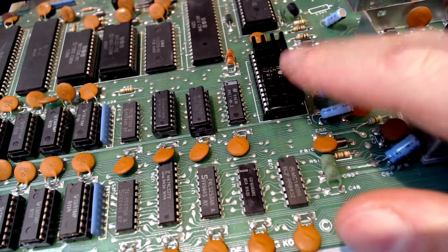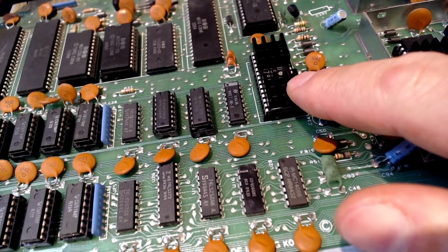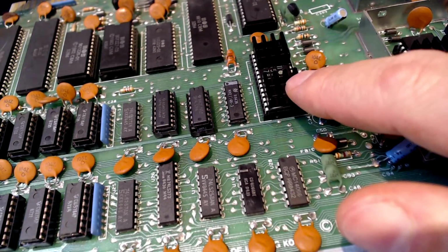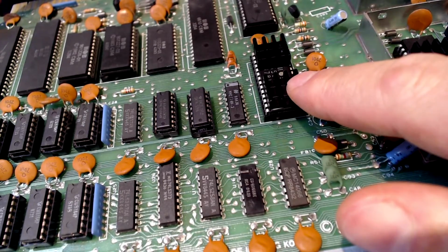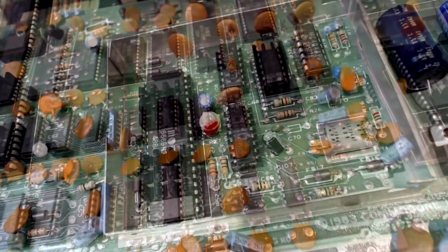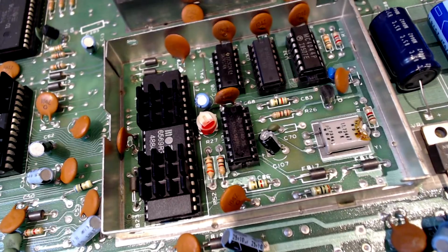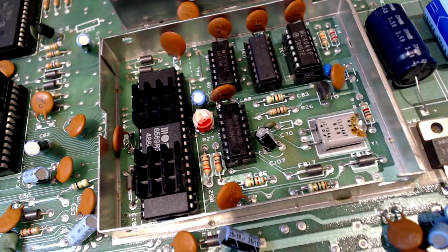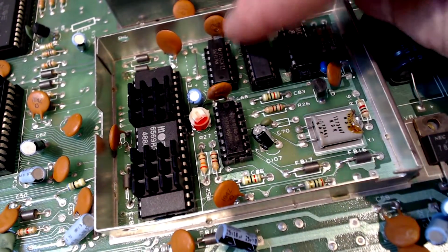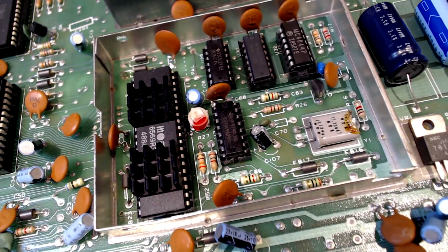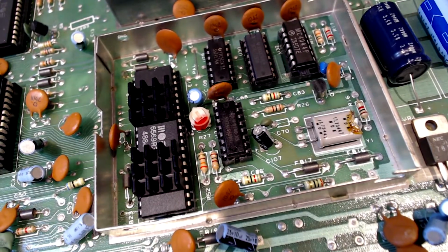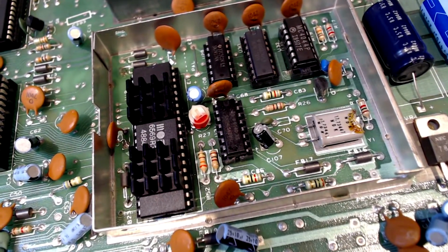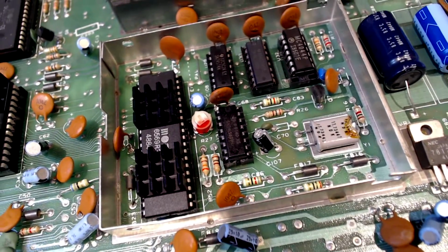I also tried to just remove that, because I think the SID may actually cause a black screen, but I removed it and there was no difference. I also socketed all the chips on the VIC-II circuit. So all these logic chips, I had to use the sockets I had on hand, so some of them are a little bigger, but it doesn't really matter.